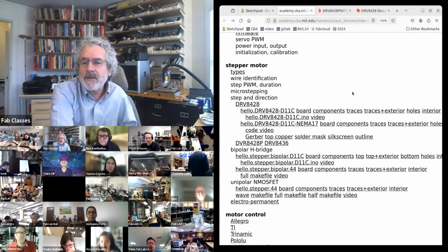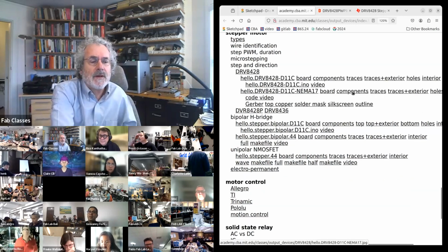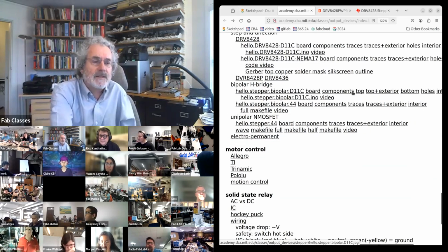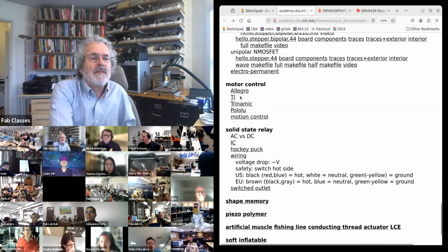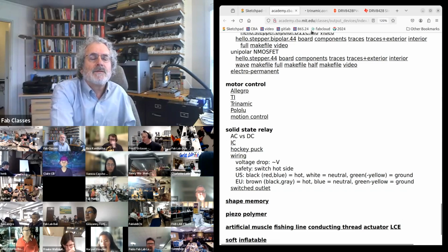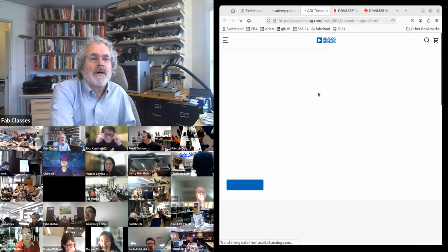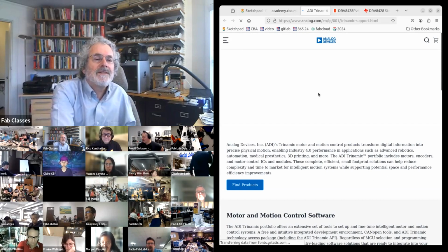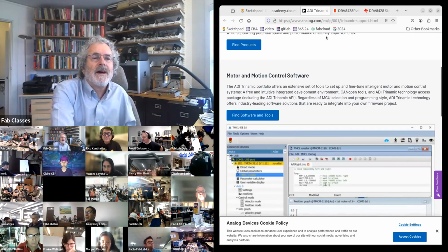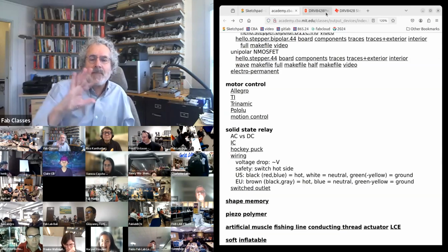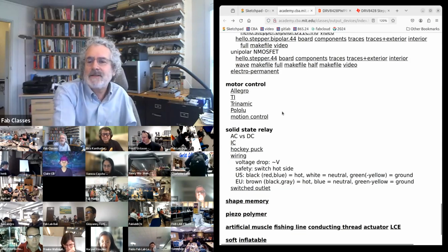I'll talk about some of the other chips in a moment. And so that's how you drive steppers. Trinamic, oh, I see. They were acquired by Analog Devices. That's more recent. They make chips that are optimized to be very quiet. And there's a question in the chat about quiet steppers.